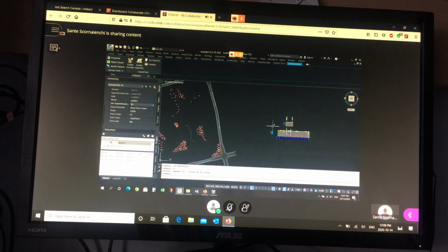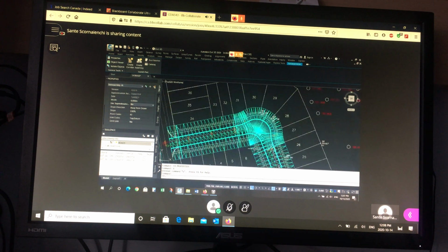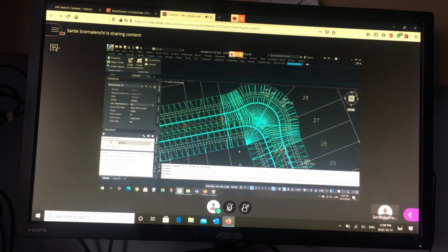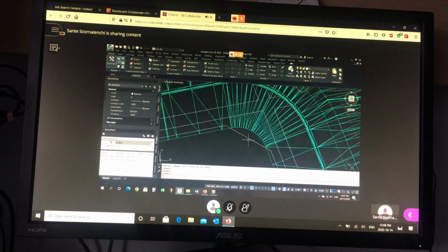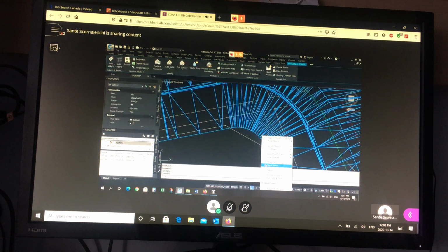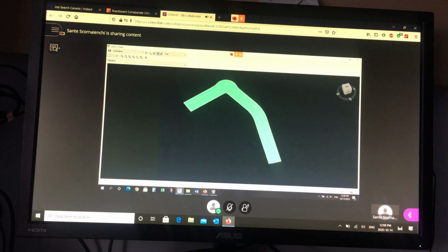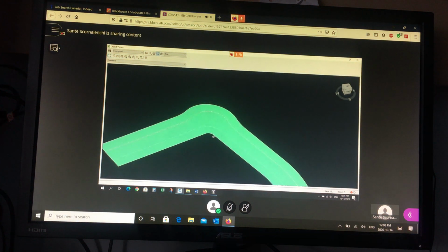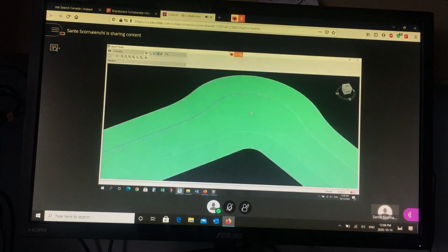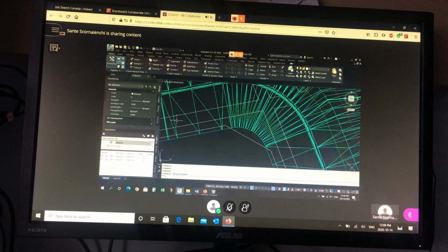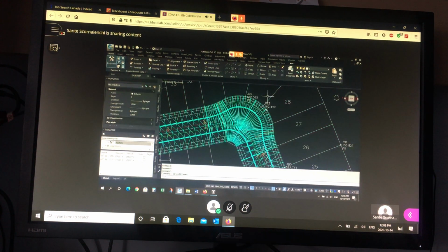So now it's going to shrink a little bit, it's still wider. Rebuild. Now it's not so bad. Now you can see the transition's nice and smooth. Object viewer, nice and clean. So that's a common mistake. Sometimes you'll see that step on the outside because the profile doesn't match the typical 20.